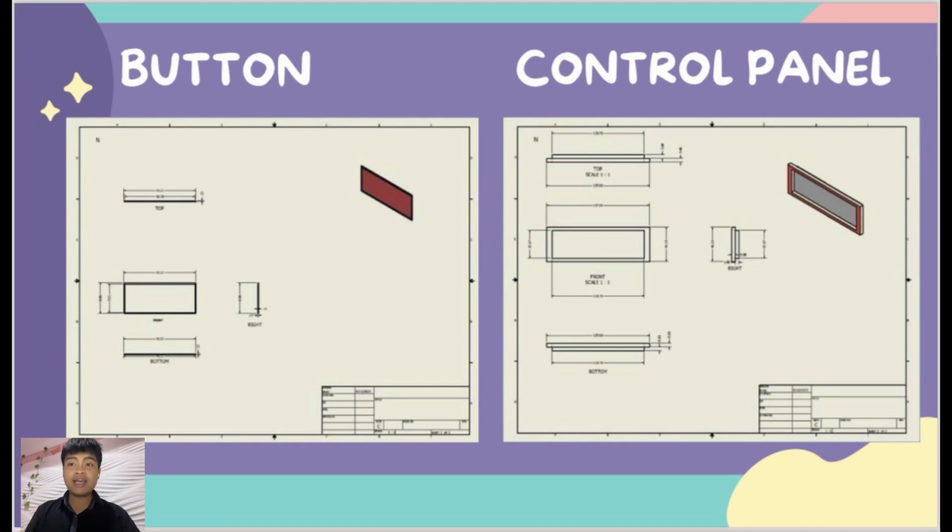As for the bottom side, it's the same. The first base is equal to 137.6 millimeters, followed by the second base, which is 123.7 millimeters, and the extrude value is equal to 5 millimeters for both sides.